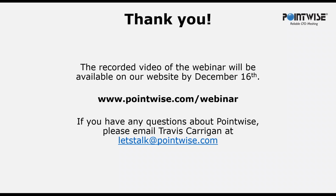You just need to be sensitive to what settings you use to create that in Pointwise. Like he said, maybe starting from a triangular mesh and pushing down. And also, you need to be sensitive to the surface mesh quality so you get the best quality hexes generated off of it and the most layers. Thank you for that question.